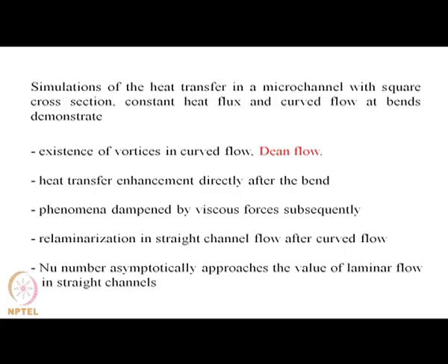There would be heat transfer enhancement just after the bend, and once you have such enhancement and such existence of vortices, the phenomenon will be dampened by the viscous forces present in the fluid. So, any vortices, which are the primary cause of heat transfer enhancement, will be dampened, and there will be reintroduction of laminar flow in the straight portion of the pipe after the bend.